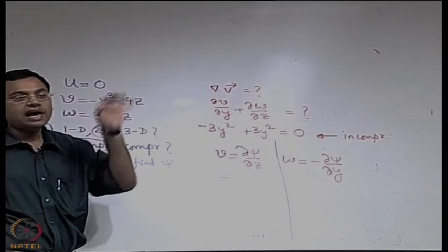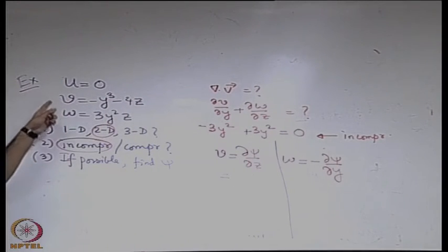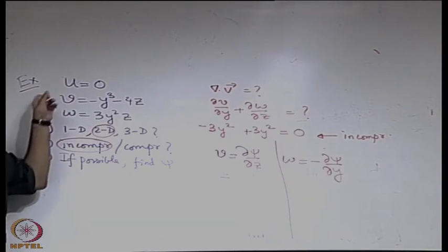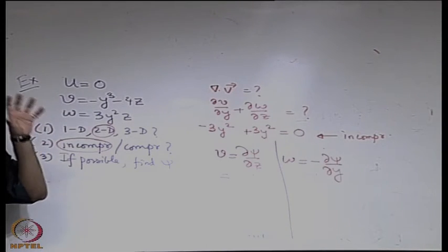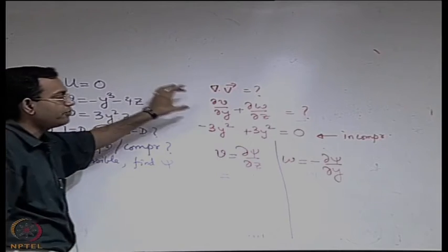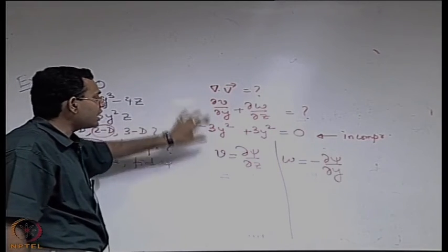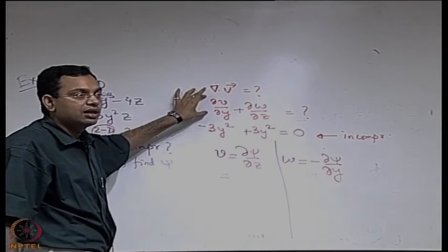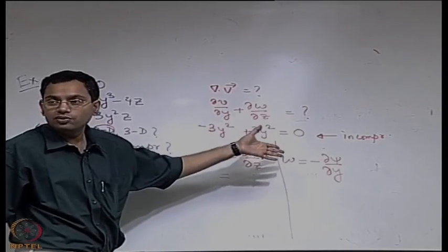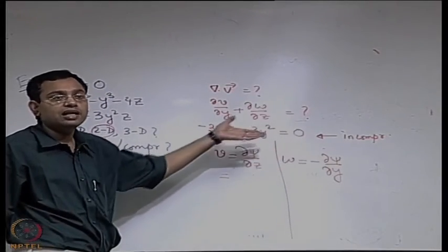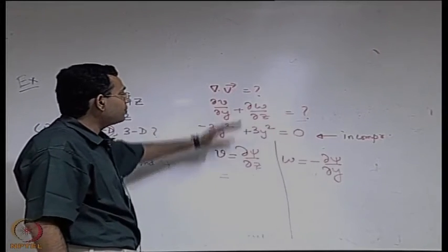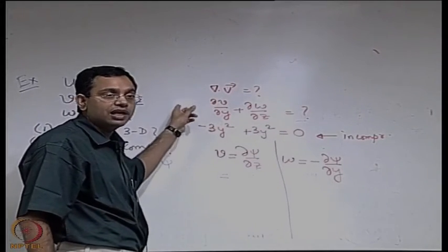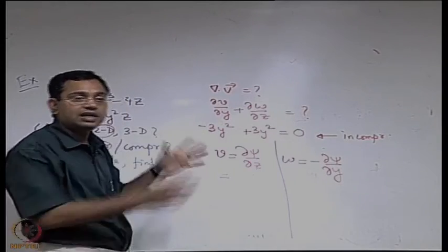Now see that with a slight change the components of velocity are given as y and z components instead of the previous ones, you see that you are facing a dilemma. That should not be there. Again the objective will be that given a form of the continuity equation, just write a parametric form which satisfies it, and that will automatically give you the definition of the stream function for that case. So do not confuse it with the case which we were discussing for developing the theory in the flow in the xy plane. Now the flow is in the yz plane, so that definition does not work here.